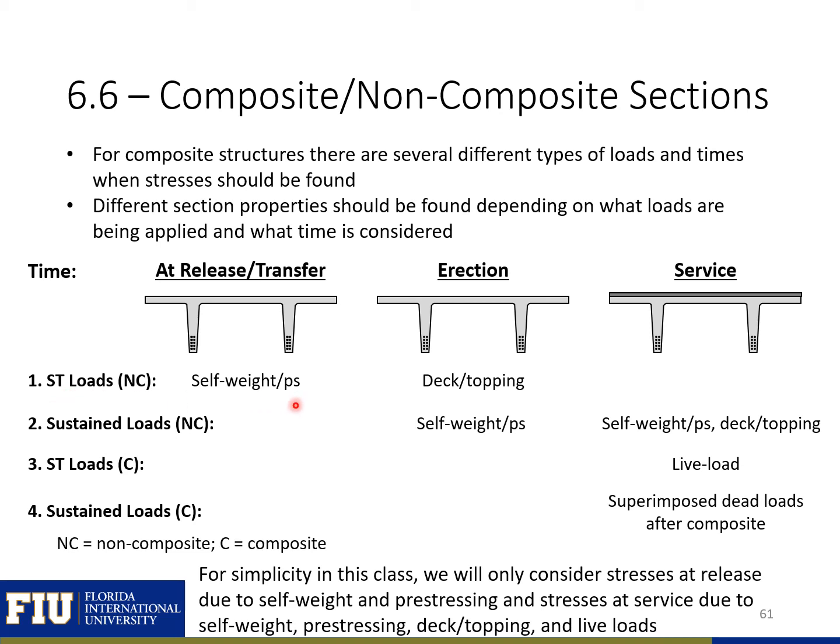When we're at erection or time of construction, we'll have the deck or topping that'll be applied to the non-composite section, and that'll be a short-term load, but then we'll have a sustained load on the non-composite section for our self-weight and pre-stressing. When we get to service, our sustained loads will be the self-weight and pre-stressing, the deck and topping, and those are all going to be on the non-composite section.